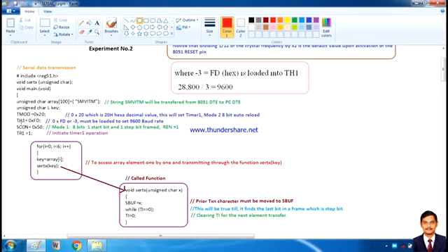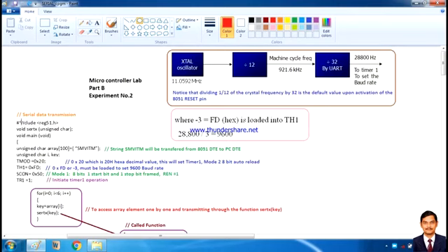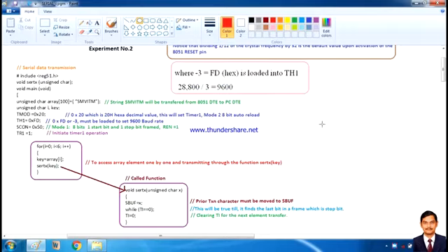Your 8051 is working with this frequency. Again, we should reduce this baud rate to achieve compatibility with your PC. So for that we have to create some sort of a delay, and for that we require a timer. The internal timer must be used.